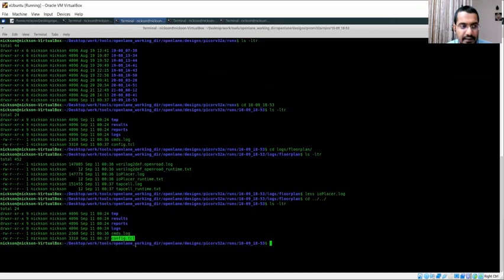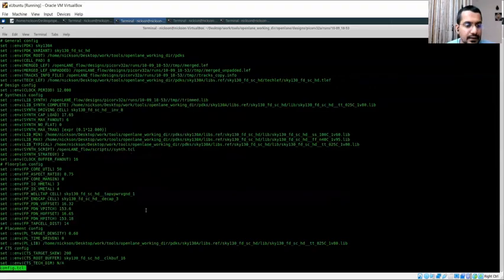This basically tells you all the configurations that are taken by the flow. So if we open this config.tcl, you can see which parameters were included in the current flow. If you look for the aspect, core utilization, yeah, this is an issue.